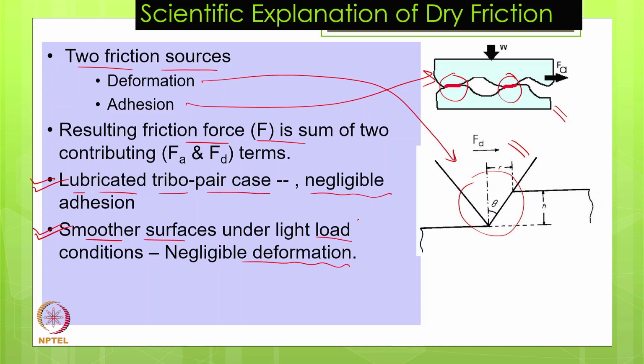However, when the surfaces are smoother, intermolecular attraction will be on a much higher side, and quite possibly adhesion will come into the picture. While in the lubricated case, adhesion will be almost negligible, and even the deformation will be lesser. So that's why we always prefer the lubricated case whenever there is a need.